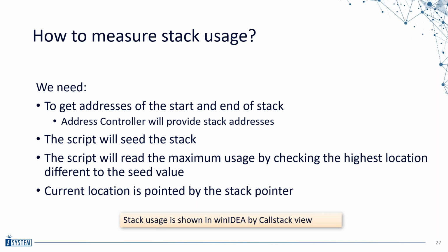We can stop or read out the stack pointer. This is the current stack usage, and we can analyze the stack memory and see what was the maximum or minimum usage of those stack, because we see up to certain level where the stack memory was overwritten over the pattern memory. So this is one short example.